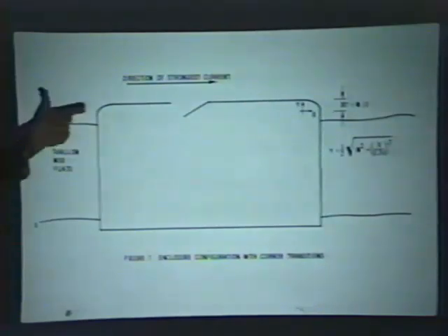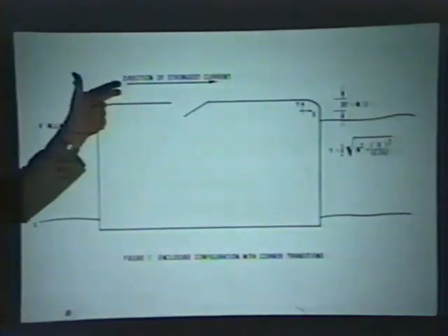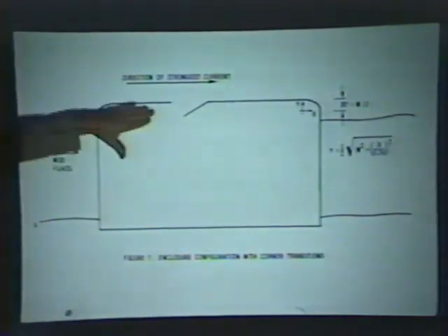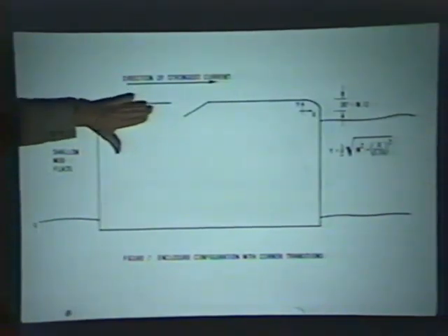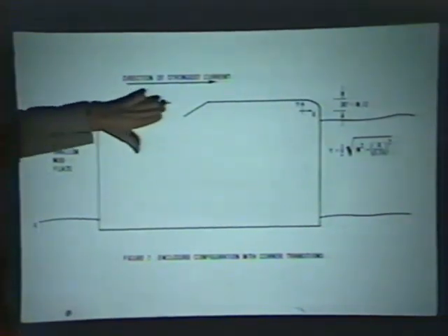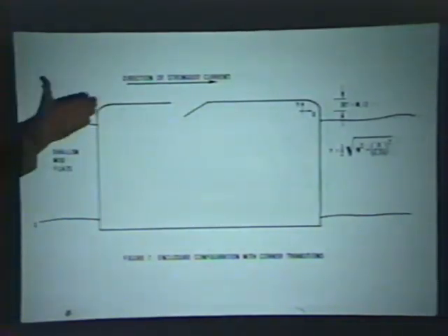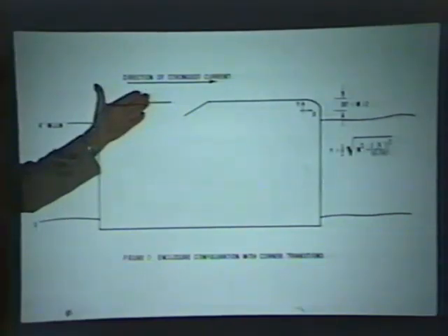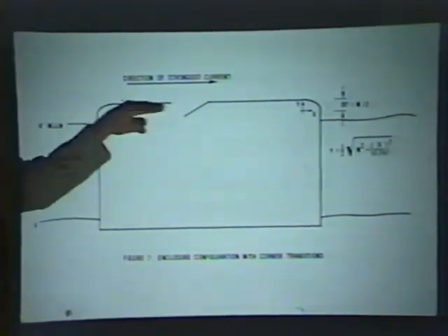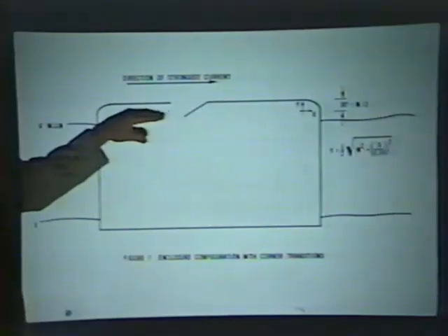So you're always torn between wanting to have it higher and wanting to keep the cost down. If it's an earth breakwater or rock breakwater, then the cost is even higher per foot of rise, or a concrete breakwater. Sheet pile isn't so bad, or wooden sheet isn't so bad.